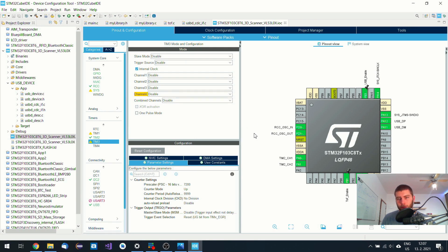That enables me to count how many seconds have passed since the last command from a computer via the virtual COM port, and after 5 seconds of not receiving any command whatsoever, this program sets the servos to the home position, which is 0 pitch and 90 degrees yaw. So that's only for that purpose. It's quite simple.